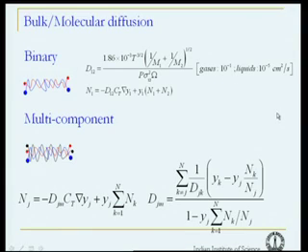per second. For liquids, the diffusion coefficients are much lower, about 10 raised to minus 5 centimeter square per second. And we all know that mass transfer is both because of diffusion, which we write using Fick's law, diffusion coefficient times the concentration gradient, and due to bulk motion of the species.